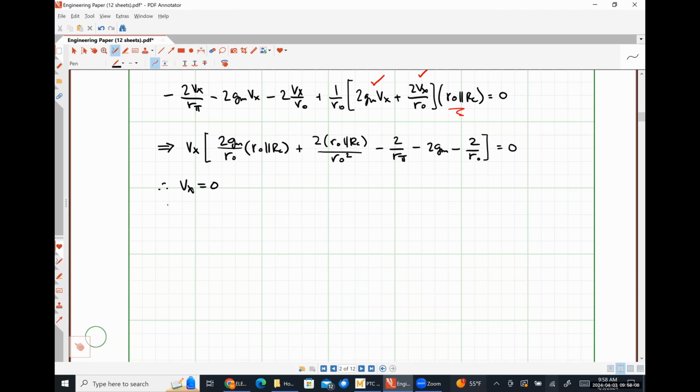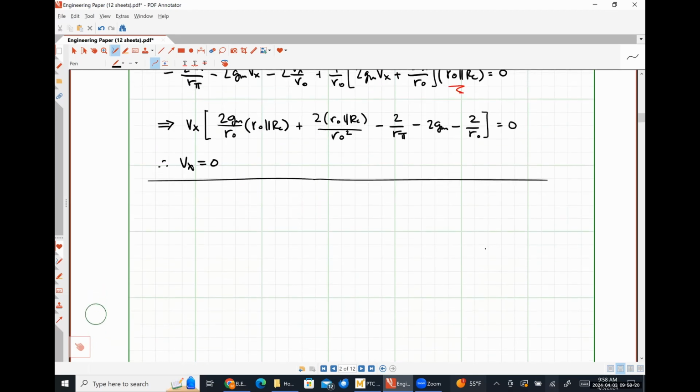So what that means is that we can actually split our small signal model into two parts and do our analysis that way, right? So on this side, I have half of my differential input voltage. Here's Rπ, VBE1.